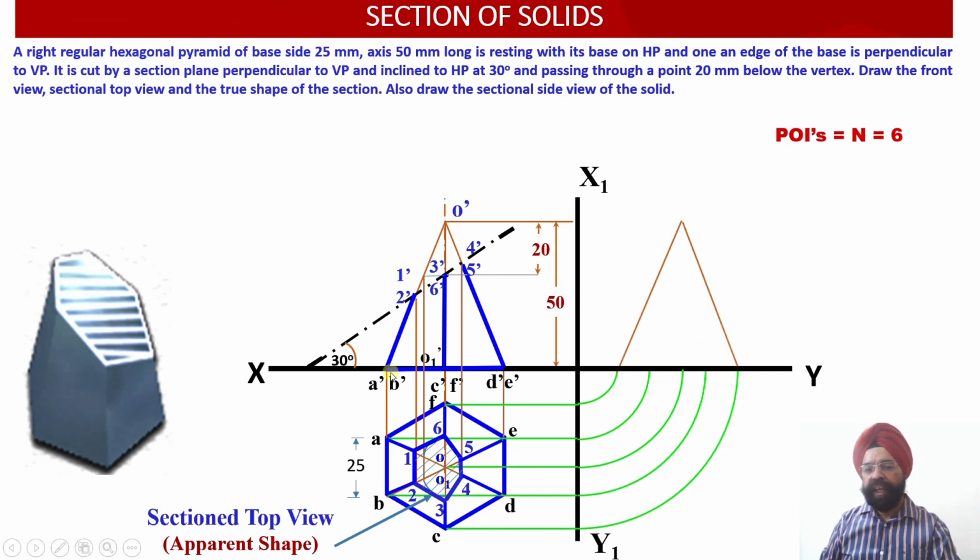So please check, A, B, C, D, E, F points, they are lying on the ground. So A double dash, B double dash, C double dash, D double dash, E double dash, F double dash, these points will be referred over here. But let us find out these points over here, because here we had the diagonal like this. A and E were coming to be there on the extreme point. Now C and F, they will be coming under the extreme point. So point F will be shifted here, point C will be shifted here.